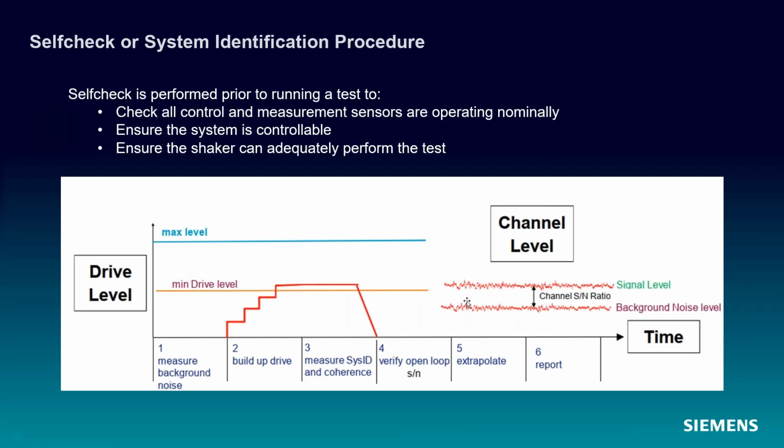You might, for instance, if you're using a laser to measure displacement during a vibration test, get an open loop error on the laser, but it might be because the laser is measuring for a particular resonance that might occur at a particular frequency, and we don't have significant enough amplitude during the pretest to hit that resonance enough that the laser can register the displacement. So there's situations like that where open loop might not be a bad thing, but 99% of the time, if you have something that comes up as open loop, you want to investigate that.